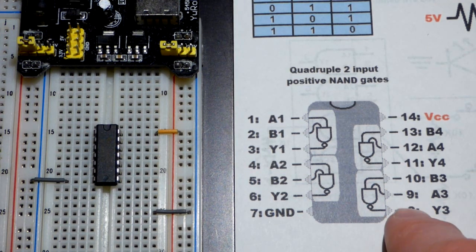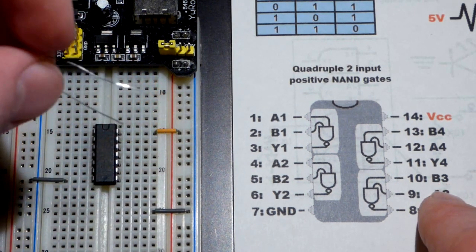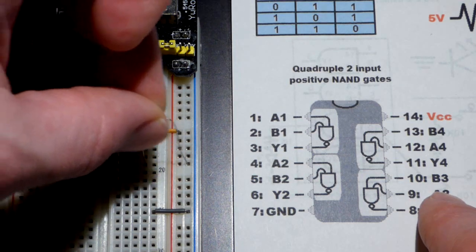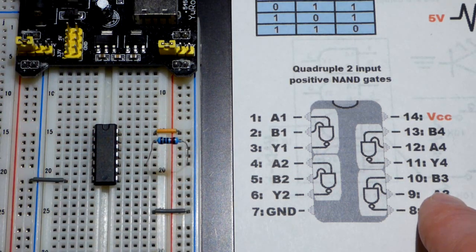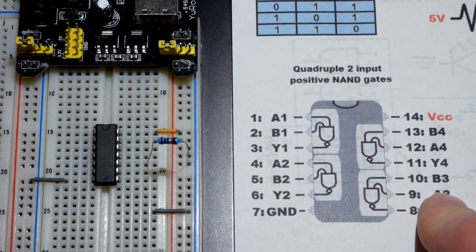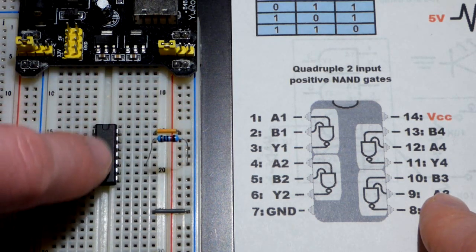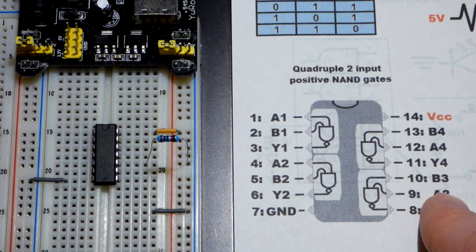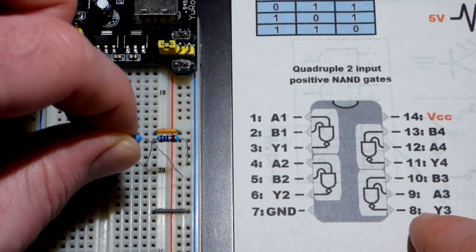So we're going to begin with our pull down resistors. So we're going to take 10 kilo ohm resistors, and because ultimately we're going to connect the pin directly to the positive rail, 10 kilo ohms is going to limit the current going from positive through the resistor to ground. We'll look at that coming up. And we just need the voltage at the pin. Current doesn't really matter with this integrated circuit at the inputs. And then we'll take the other one and go to the other input directly to the negative rail.